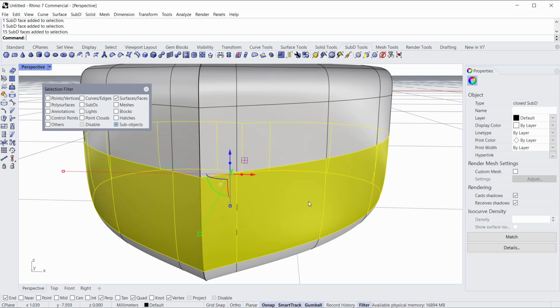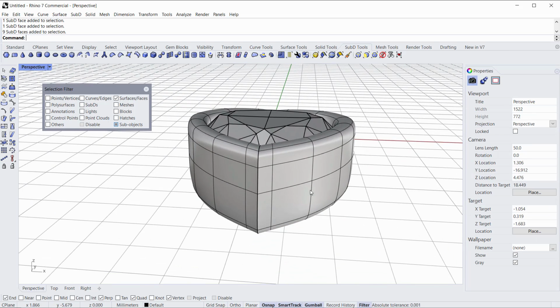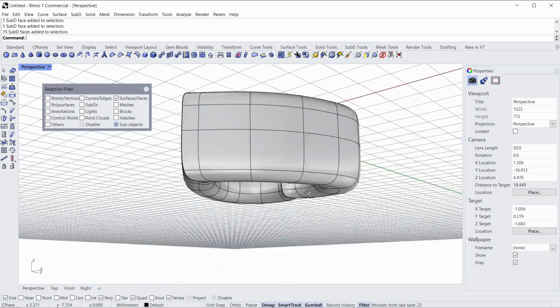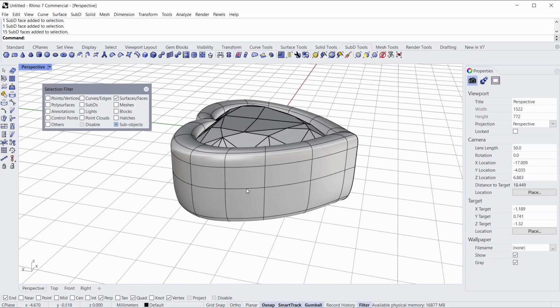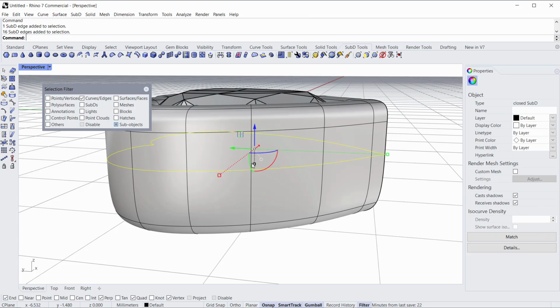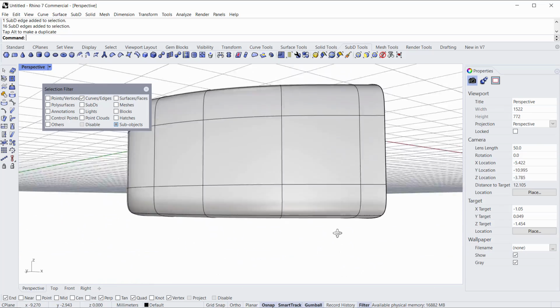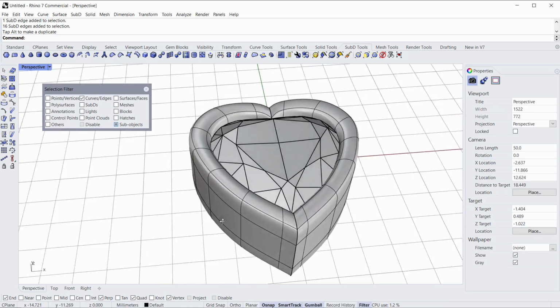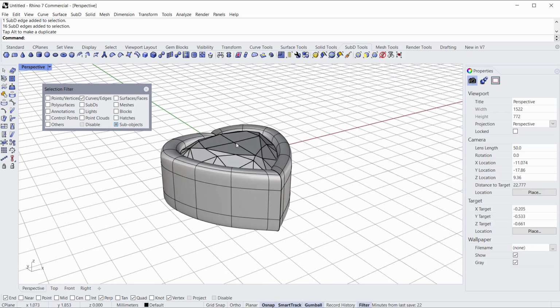And you double left click the second one and it'll go around. So if we wanted to go up, we would do it like that. So a little bit trickier than the edges, but pretty easy once you kind of know the secret. In fact, you can see how we have an edge up here, and these aren't equally spaced. So I'll go back to that edge mode, and I'll just drag this down a little bit, and that'll help square up the bottom of that bezel a little bit more. Okay, I think our bezel's good enough for what we're doing right now.